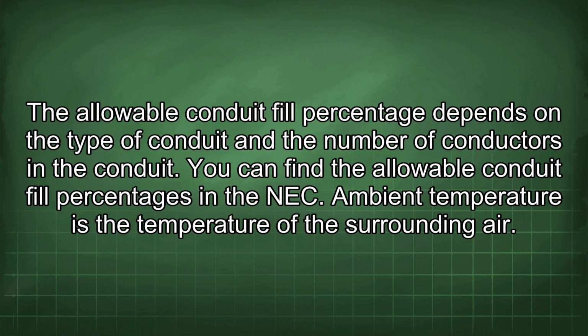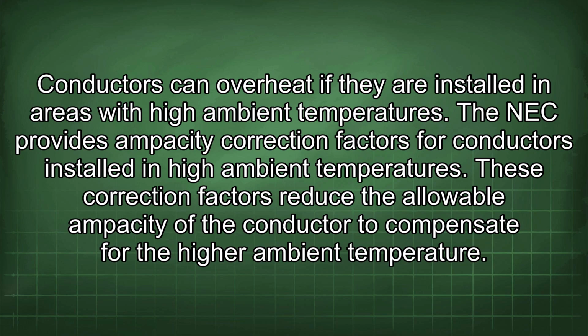Ambient temperature is the temperature of the surrounding air. Conductors can overheat if they are installed in areas with high ambient temperatures. The NEC provides ampacity correction factors for conductors installed in high ambient temperatures. These correction factors reduce the allowable ampacity of the conductor to compensate for the higher ambient temperature.